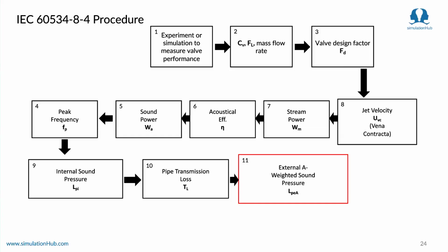But as we move along in the steps, getting the jet velocity, then getting the acoustical efficiency, all of these parameters actually depend on sub-parameters. They depend on a parameter called FL, which you might have heard of, the liquid pressure recovery factor. Also, they are dependent on XFZ, which is the incipient cavitation index.